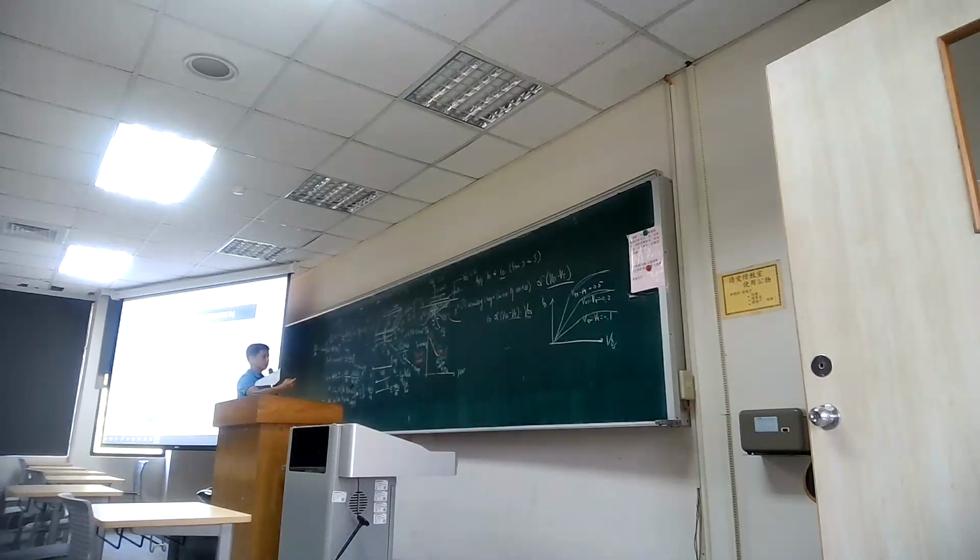Okay, so you can see the ID is pointing in from drain to source with the mu n C outside W (VGS minus Vx minus Vt) dVx. So that will be similar to this one. Okay, you can check the sign. I didn't carefully track the negative or positive sign here, but eventually you get the ID pointing in from drain to source.